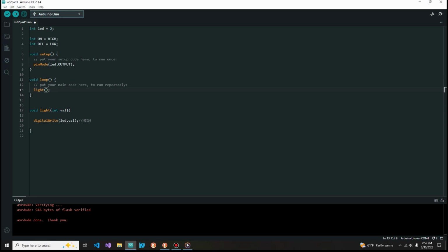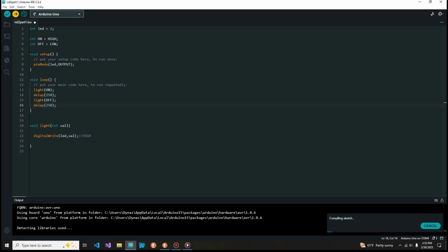And remember from earlier, we have on, and then we can go delay and say, well, we'll do 250. Why not? And then we'll just come down here again, light, and then we'll say off, semicolon to terminate the line, not colon, semicolon, and then we'll give it another delay, 250, right? Now once that's done, it'll work exactly the same way as we have before, but now we're doing it through the use of a function.